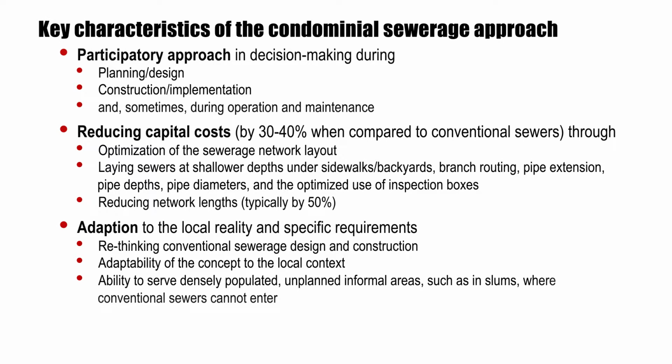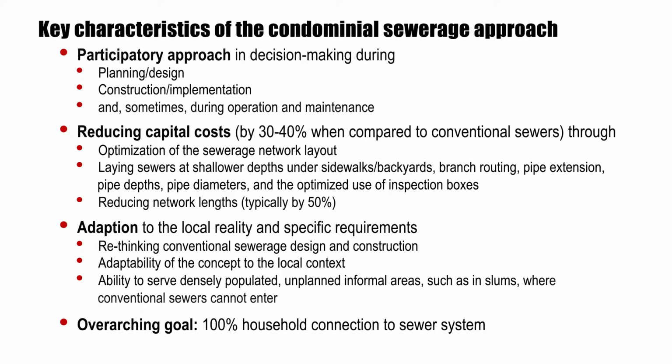The condominial approach to implementing sewers provides us with the tools to depart from conventional thinking on the design principles of sewers. It thus allows us to design sewer systems that can be successfully implemented in densely populated, unplanned, informal areas, such as in slums. One of the guiding principles of the condominial approach is to achieve a 100% connection rate of households, whether they are located in rapidly expanding poor informal settlements or in middle class or rich areas of the city.